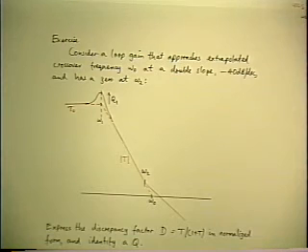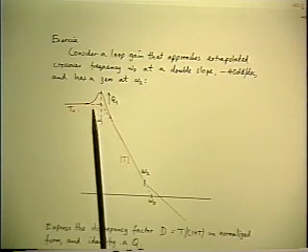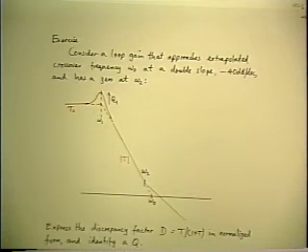And if you close a feedback loop around that switching converter in order to make a switching regulator out of it, then the loop gain is proportional to the transfer function of that LC filter. In other words, the LC filter characteristic shows up as part of the loop gain, which is why it's shown right here.